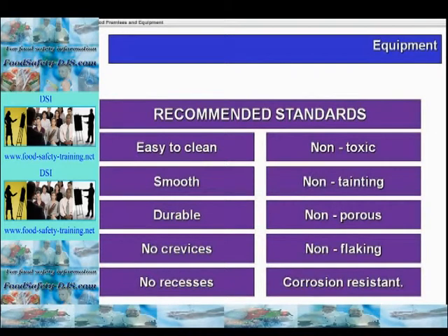Regulation EC 852/2004 requires that food contact equipment and fittings are kept clean, disinfected at a frequency to avoid any risk of contamination, constructed to minimize the risk of contamination, to enable thorough cleaning and disinfection, can be disinfected when necessary, and installed so equipment and surrounding areas can be clean. In addition, the following is recommended.